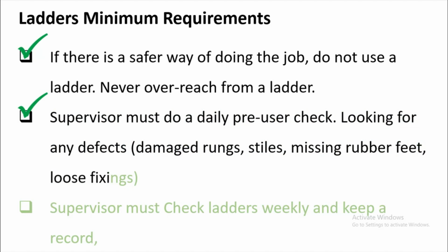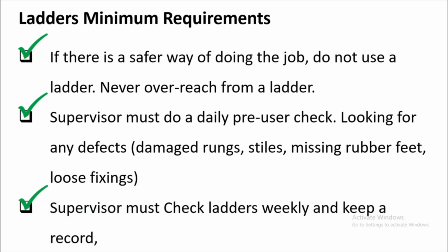Supervisor must do a daily pre-use check, looking for any defects, for example damaged rungs, stiles, missing rubber feet, loose fittings, etc. The supervisor must do it every day before he allows his workers to use it, and make sure that he knows how to inspect those things.